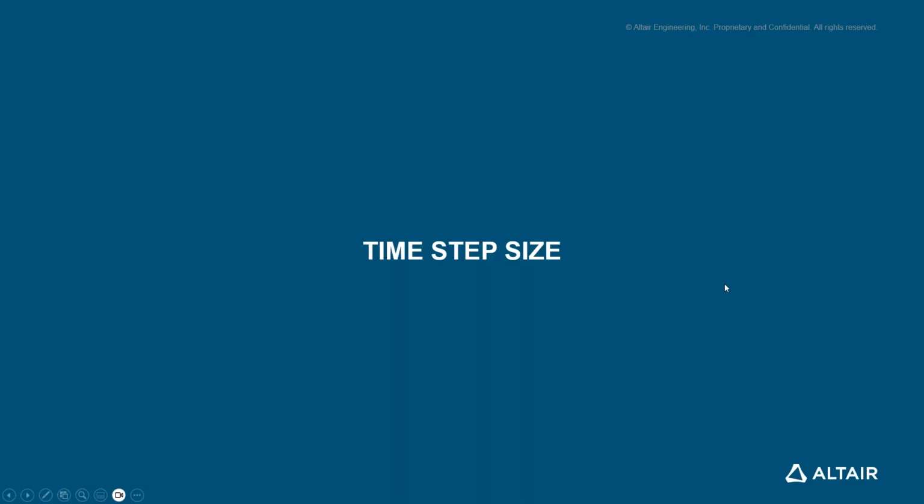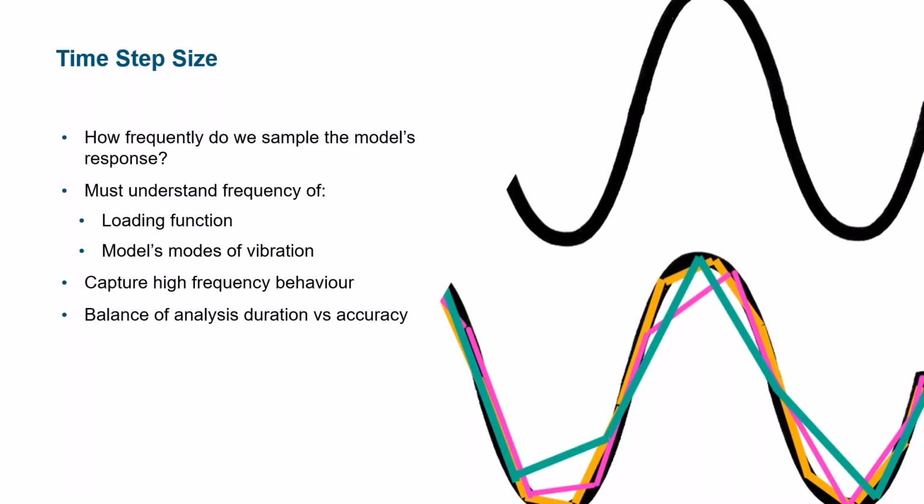So time step size is obviously very important. And to understand the time step size, we have to understand essentially how frequently we want to sample the response of the structure. And I've done my best to illustrate this with a very crude drawing, as you can see, a very colorful but crude drawing.